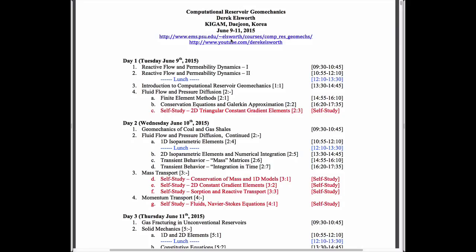And so since we have three-dimensional flows, we basically solve F equals ma, Newton's second law, in x, y, and z, in the 3 directions. And then we have another equation that constrains them, which says that mass rate in equals mass rate out. In other words, we solve 4 equations. One is a continuity equation, which we defined here, same one, but also 3 equations for F equals ma in the x direction, F equals ma in the y direction, and F equals ma in the z direction, and then solve them. And so that is where we solve for momentum.